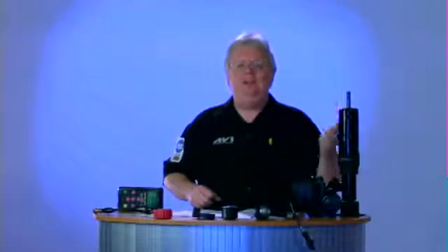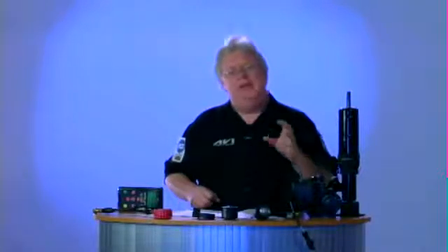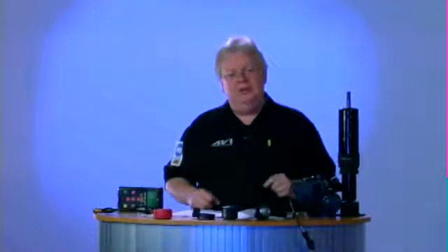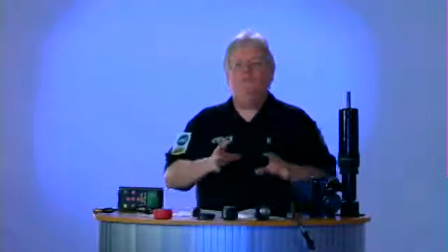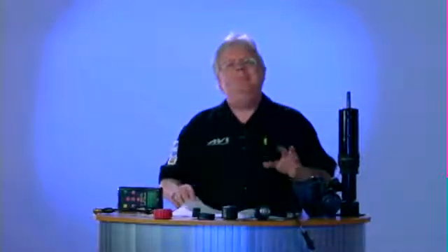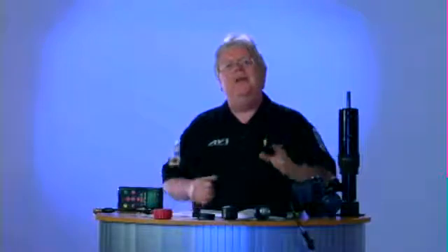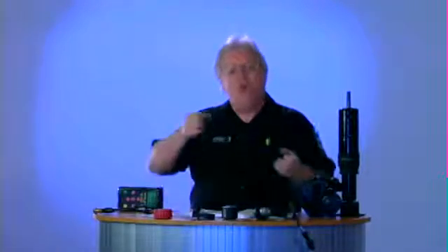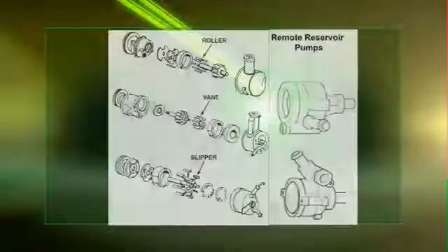And if you have a loose belt or a glazed belt, a defective belt that needs changed or adjusted, that's when you hear the squealing noise. So most techs know this. Maybe you're one that's not worked on this particular area of the car before. Maybe you've been a transmission tech and you're moving into chassis and steering and so forth, or you just want to get master certified. It may not be that obvious, but that's been a long time problem. As you turn the wheel and you hear the squealing, it's a power steering belt that's loose.